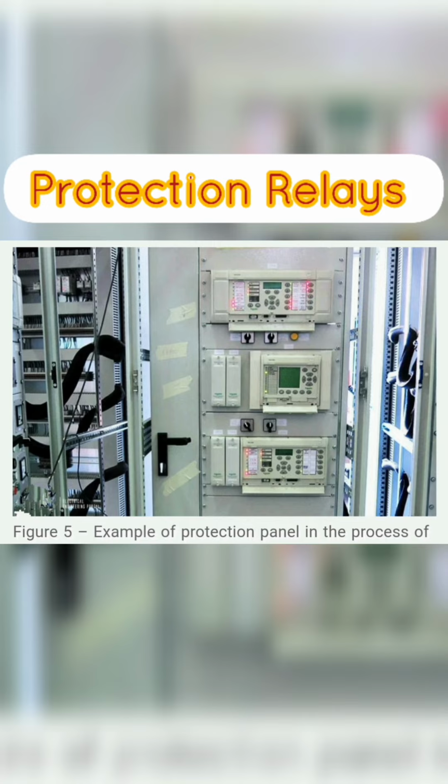Next we learn about sensitivity, selectivity and speed. Sensitivity, selectivity and speed are terms commonly used to describe the functional characteristics of any protective relaying equipment. All of them are implied in the foregoing considerations of primary and backup relaying. Any relaying equipment must be sufficiently sensitive so that it will operate reliably, when required, under the actual condition that produces the least operating tendency.